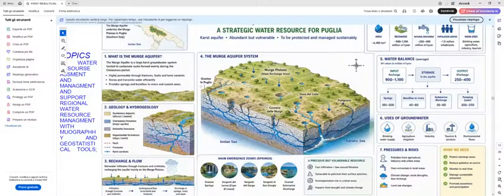springs and base flow to rivers and coastal areas. So the main geological units, as we just said, from a cross-section between east and west: we have the Quaternary deposits, and the Cretaceous limestone that contains the major aquifer. In the subsurface you have the dolomitic limestone, and deeper still you have impermeable formation. So the faults make the major connection between aquifer parts with different piezometric levels.